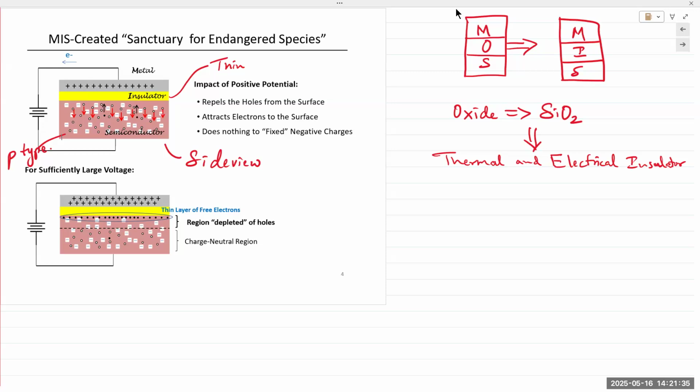It's a capacitor. So capacitances are a big deal in transistors, especially FETs, MOSFETs. We are, again, not going to spend too much time on it right now. But that results in a capacitance, right? So there is a capacitance because of the physical construction of the device itself. You have two conducting plates separated by an insulating material. All right, but everybody with me so far?